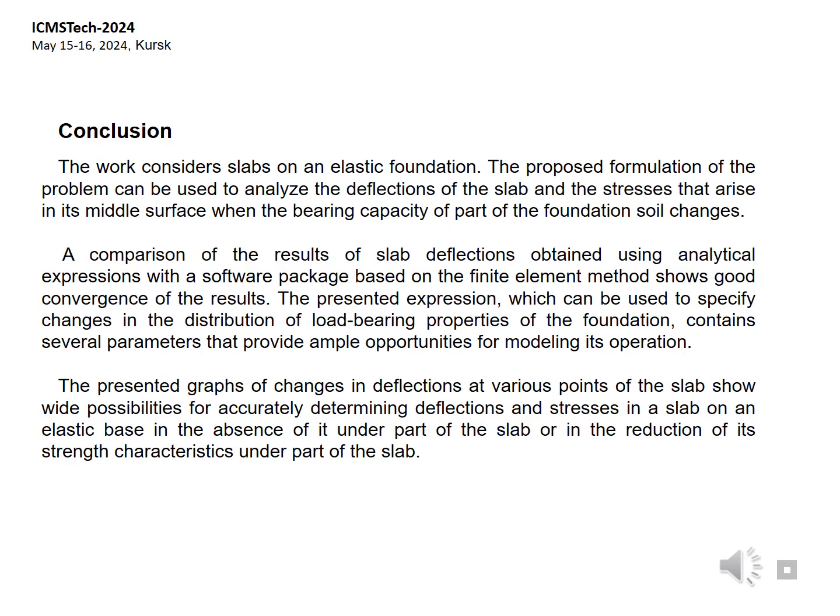A comparison of the results of slab deflections obtained using analytical expressions with a software package based on the finite element method shows good convergence of the results. The presented expression, which can be used to specify changes in the distribution of load-bearing properties of the foundation, contains several parameters that provide ample opportunities for modeling its operation. The presented graphs of changes in deflections at various points of the slab show wide possibilities for accurately determining deflections and stresses in a slab on an elastic base in the absence of it under part of the slab or in the reduction of its strength characteristics under part of the slab.